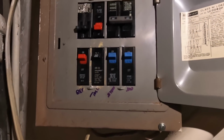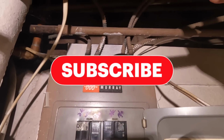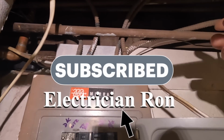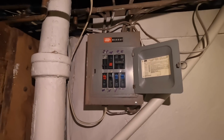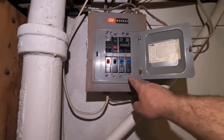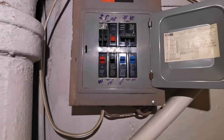But mostly what's going to happen here is a lot of these conductors up here are actually going to go into a junction box, and then we're going to extend it with either some PVC or some EMT from the junction box back to the new panel location. It's 4 wires, so we're good there. I think it's on a 30 amp circuit. And this is the dishwasher, the refrigerator, and a bunch of stuff in the kitchen.